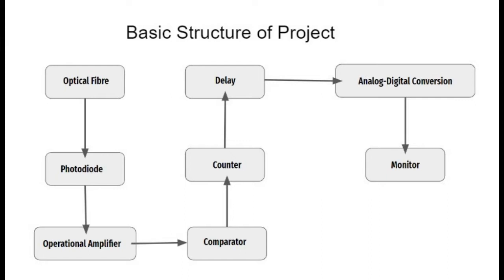The output of the photodiode is given to a signal conditioning unit, that is in our case a transimpedance amplifier. The transimpedance amplifier or the TIA circuit is an I to V converter, that is current to voltage converter. Now to build this circuit, we have used LF356 op-amp because it functions at higher frequencies.